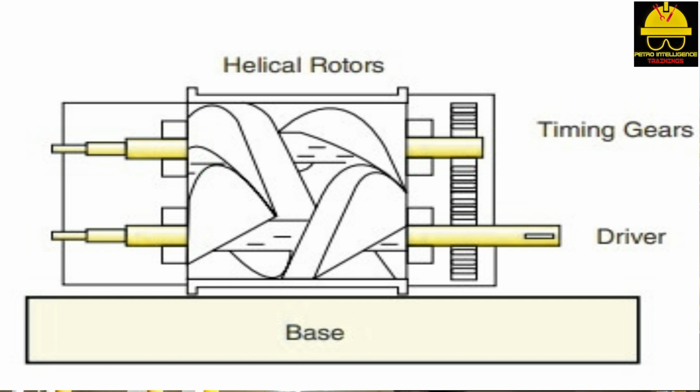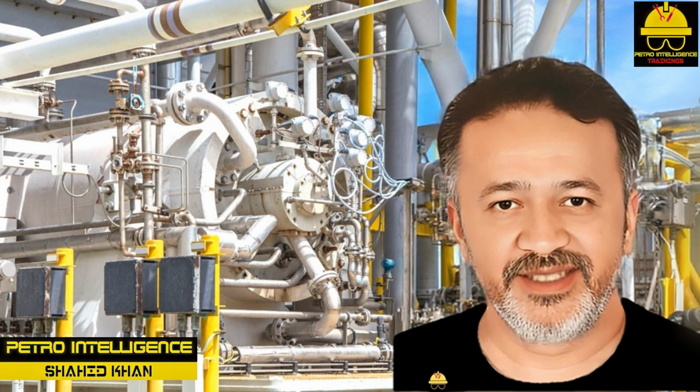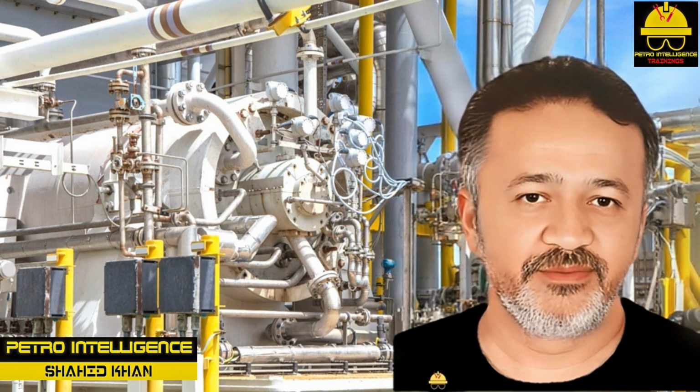Rotary screw compressors operate at speeds between 1,750 and 3,600 RPM and have capacity ratings above 12,000 CFM, cubic feet per minute, on the inlet volume and discharge pressures between 3 and 20 psig. Some rotary screw units can operate between 60 and 100 psig.